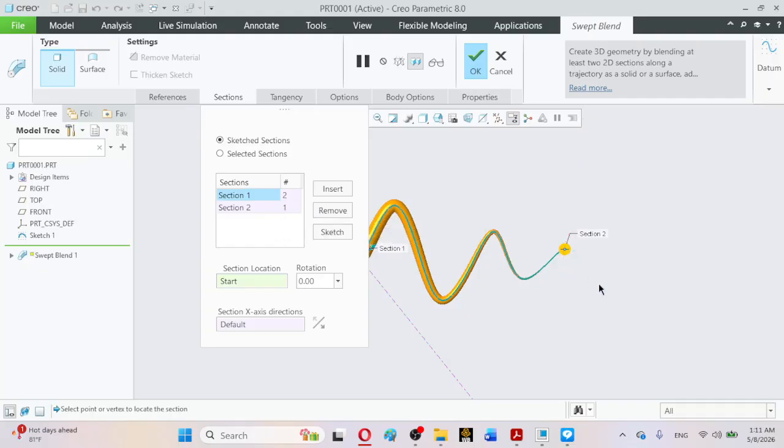So we have actually learned a very important conclusion here: the number of segments in each section must be the same, except when the point cross section is used, because if the point cross section is used, then only one segment can exist there.